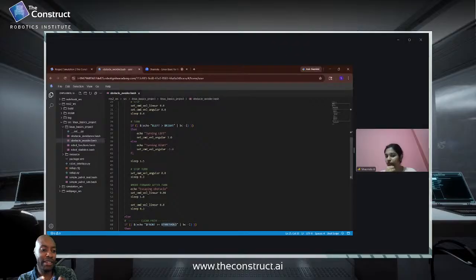I wanted you to have some logic that tells your robot how much to turn. That's the whole point. Because if you have a camera that gives you a little bit more than a standard, or if your processing algorithm has got more resolution, that means more cases. Instead of 3 cases, maybe you have 5 or 8 cases, for example. That means you also have to adjust the logic that is setting your angular and linear velocities accordingly so that it uses that resolution correctly. It turns just enough, but not too much.